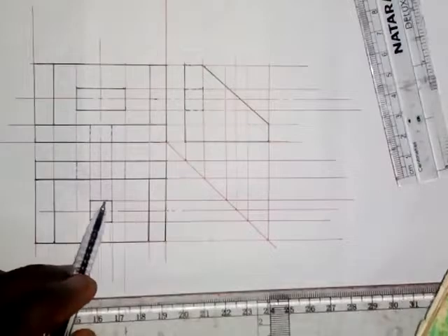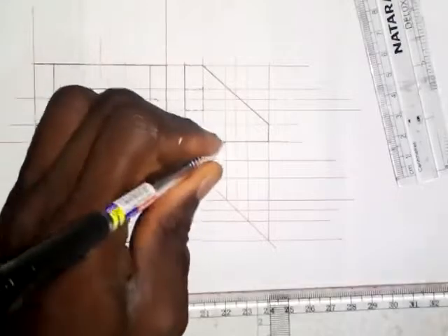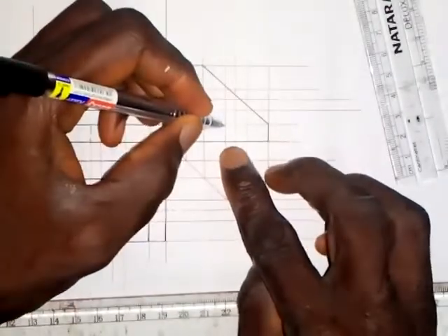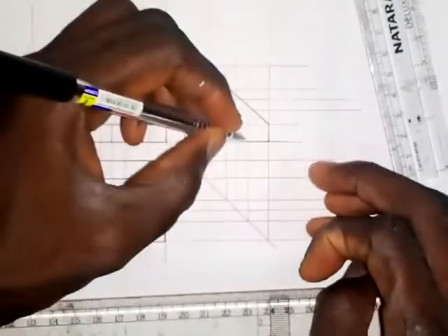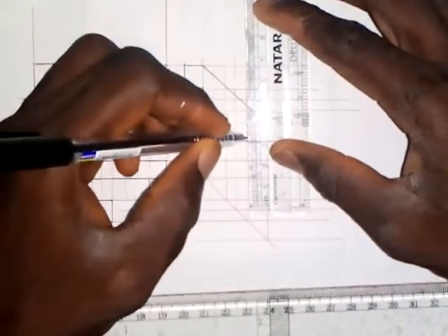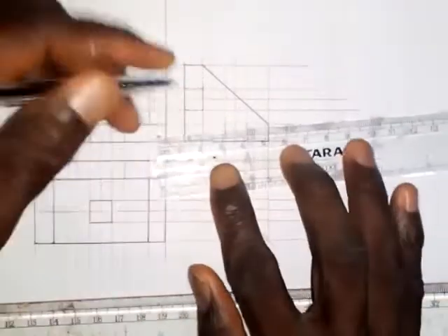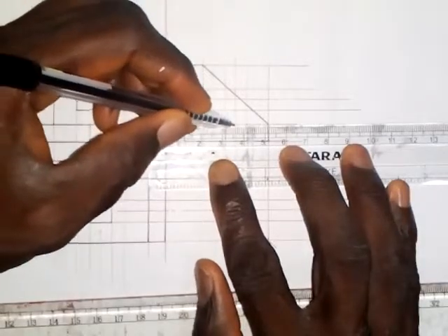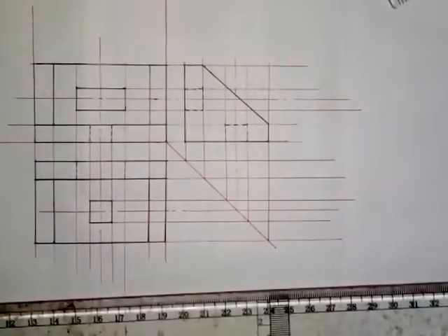Then what about this one? It's around here, so I just need to follow this line, then go up like this. This is the starting point. If I follow it from here, this is the end point, then we have this point. Just need to follow this. When I follow this one like this, I have it here. So I'll put this here like this, short dashes line, and this also short dashes line. Over here also I will produce a short dashes line. Okay, so that is the end elevation that we were asked to produce.